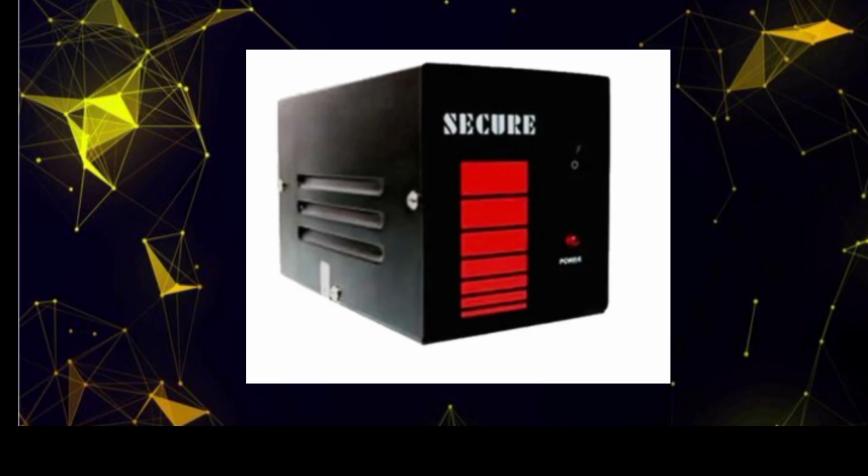Exciter stator: stationary part of the exciter system that produces a small AC voltage to power the main rotor's field windings. Rotating rectifier converts AC from the exciter rotor into DC, which supplies current to the main rotor field's windings. Exciter rotor: rotating components of the exciter that receive AC from the exciter stator and send it to the rotating rectifier.